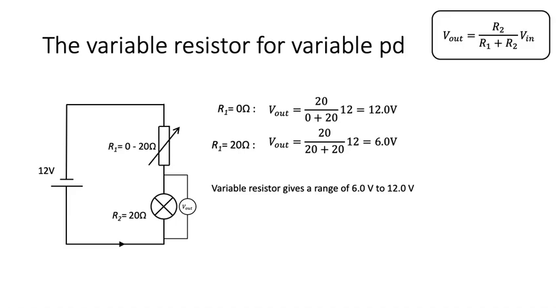We can, of course, increase the resistance. We could put a different variable resistor in if we have one available, but even there, the problem is that no matter how large you make it, it's still going to have some potential across the lamp. It's never going to go completely to 0.